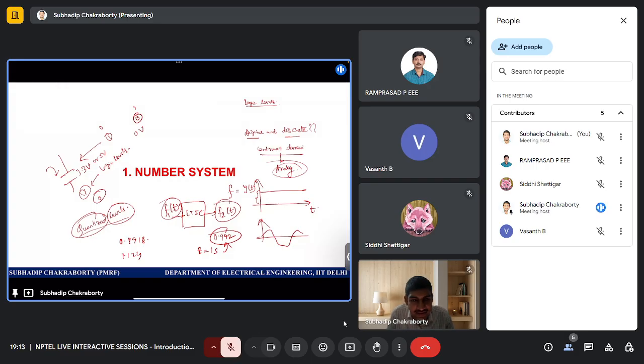So to make it digitalized or discrete, we have to define some quantization levels where the network itself identifies the logic to be 1 or 0. And once we have this 1 or 0, the quantization in the levels of voltage corresponding to the logic levels, then we say we are in the digital domain. Why is digital so popular or so easy? Any idea?